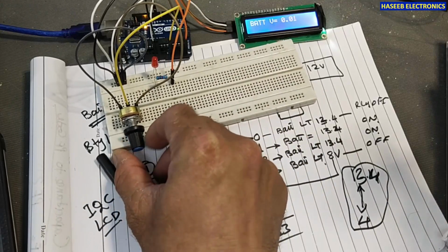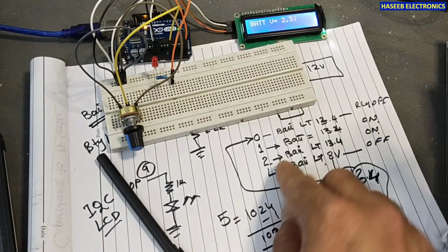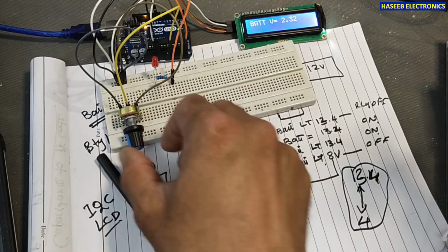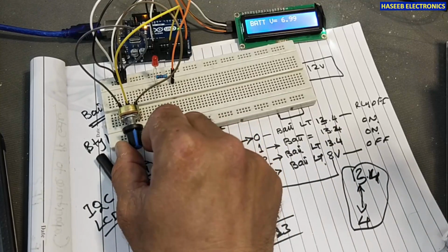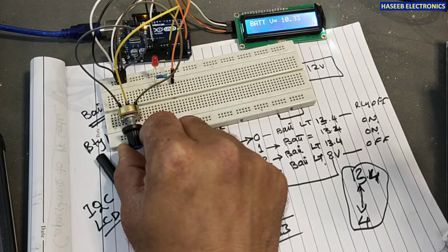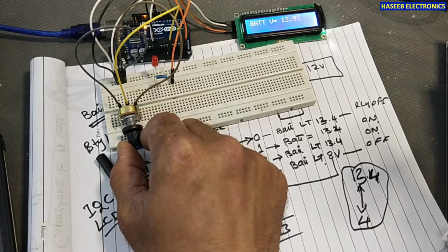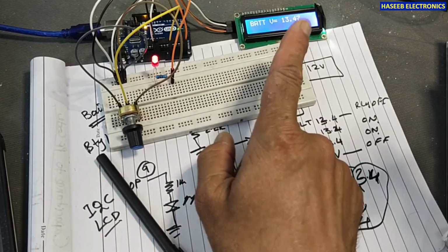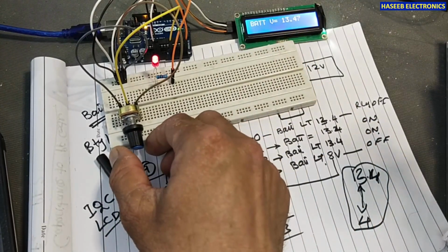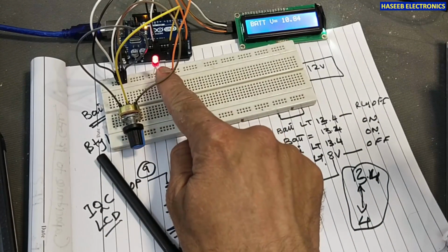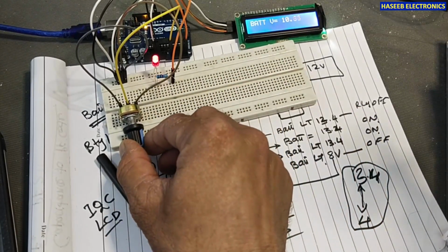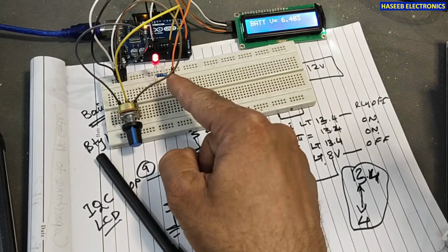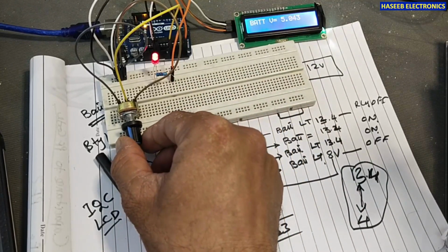We can see the battery is now 0. This is our first condition. BMS is 0, voltage is less than 13.4 volt. Now the battery is charging. When we reach 13.4 volt, 13.3847, yes, it is now charged. We can display some message here as well. But now when the battery is discharging, because the relay is on, it is disconnected. 6.7. Before this at 8 volt it was disconnecting, but now 5 volt.